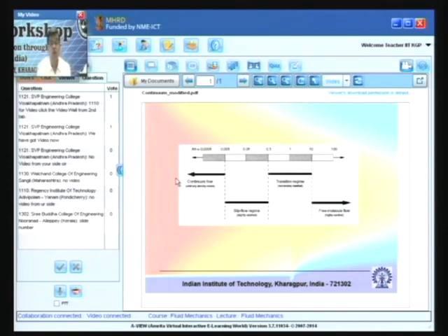It is written there, no slip condition. That means not only will the continuum approach be valid, but at the surface, Professor Suman Chakraborty explained that boundary conditions are very interesting for fluid flow, which depends upon the interaction of the fluid with the boundary. No slip condition is a condition which will be discussed afterwards in detail, that the flow velocity with respect to the solid surface, at the solid surface, is 0. That is known as the no slip condition.